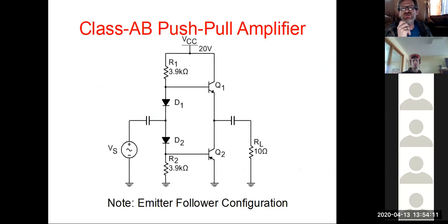So we can see here we still use the push-pull style. But notice in between, now we have two diodes tied in here, and remember the way they work: we get either forward bias or reverse bias, and we get the 0.7 volt drop across. And remember how it behaves in reverse biasing. So like I said, the way this configuration is with the AC alternation going in with it, it never lets either of those transistors turn completely off. So at all points, they're still transmitting somewhat, just not ideally, if you will.